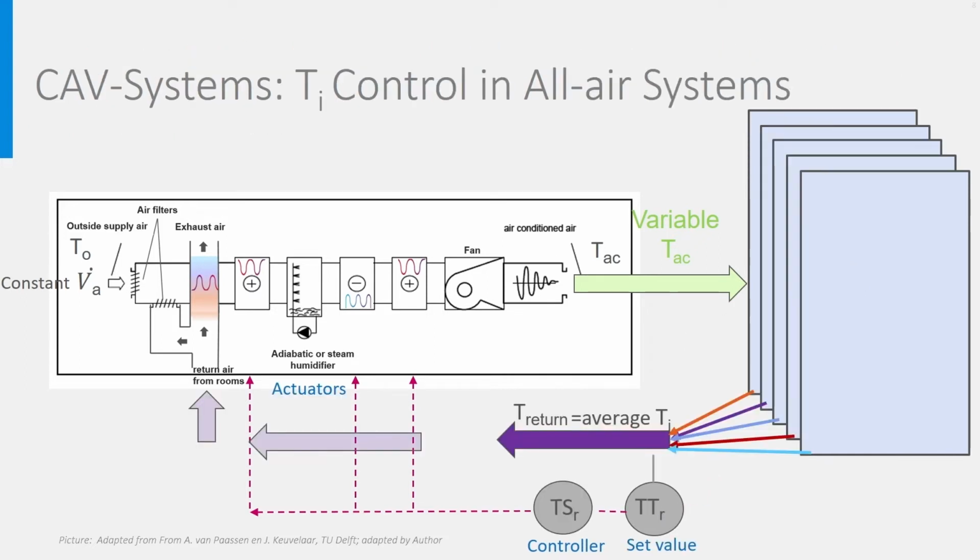The heat and cold demands in these rooms, as well as their temperature, will differ depending on their location and occupancy. On which room thermostat will the control be done? We can choose one room, but then all others will be too warm or too cold, most probably. The solution there is A. To design zones correctly, meaning that in an HVAC zone it is important that all rooms have quite similar behavior, and B. To average on all rooms.